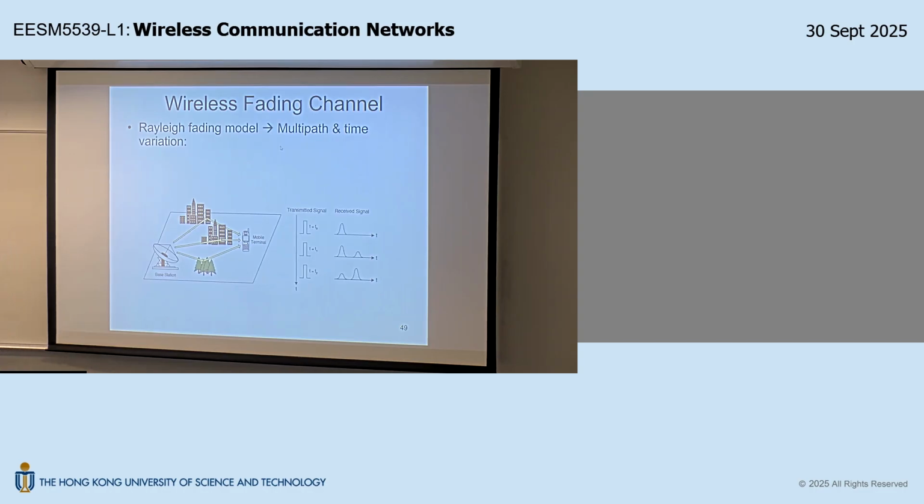Is that okay? So that means when you stumble into the bright spots versus the dark spots, the difference in receive power can be up to 30 to 40 dB. The reason is that even when you are in a dark spot, your destructive superposition will not give you 0, right? Because you are not only talking about two paths, you talk about multiple paths together. So it never cancels to zero. So you still have some power.